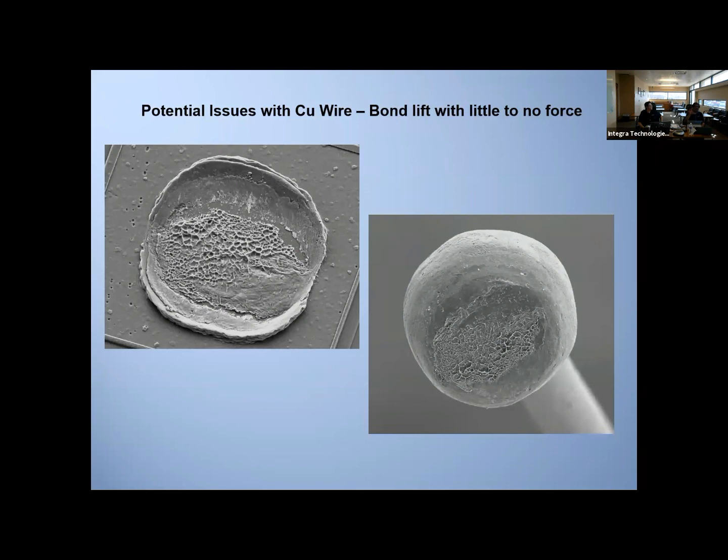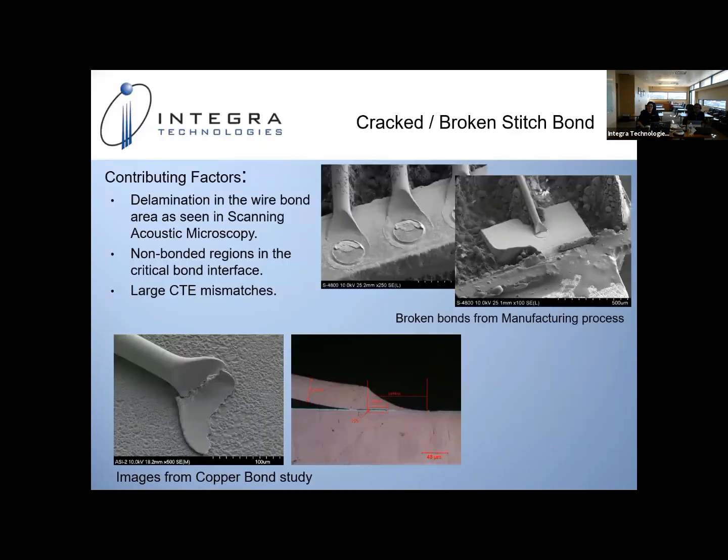There was not a good scrubbing motion going on, and it's just a bond wire practically sitting on the pad making contact, but obviously you have a lot of intermittency during actual device operation. Yeah, in your previous slide you had a clear case of overbonding, and here is what we consider underbonding. Where it's just sitting there and there may be some chemical residues that left it dirty, if you will, and caused it to perform the way it did at bond pull. Or the scrubbing was not done right. Fair enough. Yeah. Great.